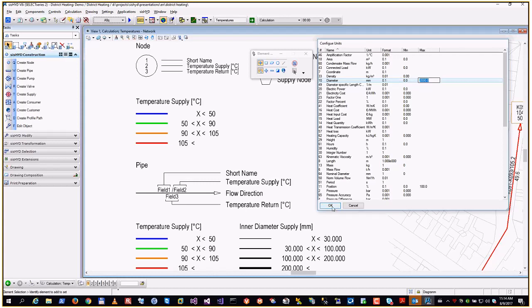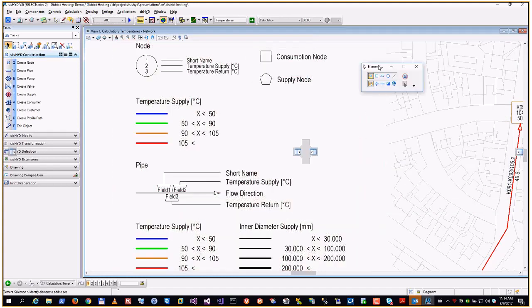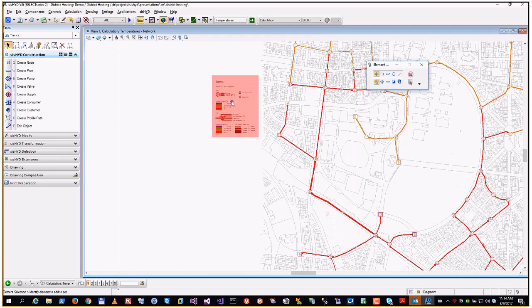We have anyway sanity checks with the log files, where if values are not viable, we warn the user in the log files. So for example, what you cannot enter is a pipe with a length of 0 meters. We cannot compute the pressure loss for it. So we'll state, hey, there is a pipe which has a length of 0, or if the diameter is missing, those situations.